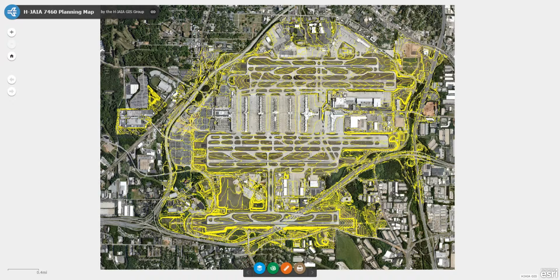First is the airport's high-resolution 2015 aerial image, and overlaid on top of it is our 1-foot contour elevation dataset. These are the two tools that our 7460 management group uses to QC and check the 7460s that you submit. So if you're using the same data they're using, the odds are you're gonna fly right through this process, determining the latitude, longitude, and elevations with no problems.